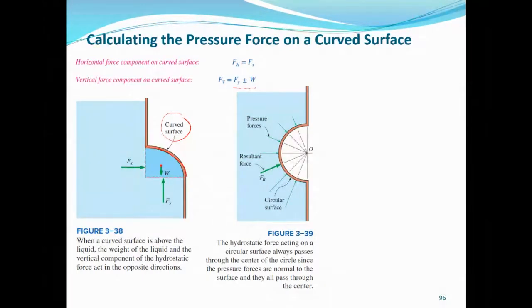And then in the second figure, when the hydrostatic force is acting on a circular face, the resultant hydrostatic force passes through the center of the semicircle, because any line that is perpendicular to the semicircle surface has to pass through the centroid of the circle.